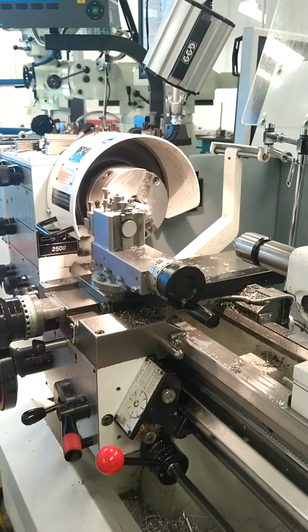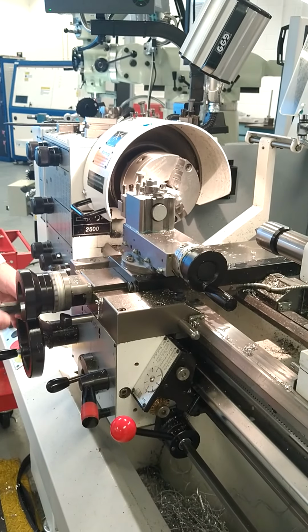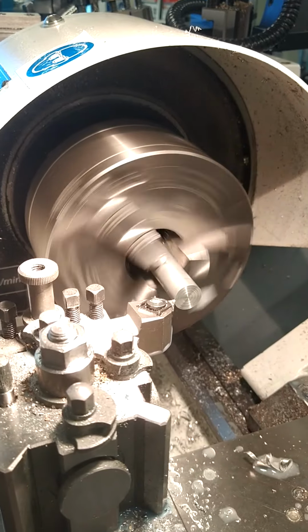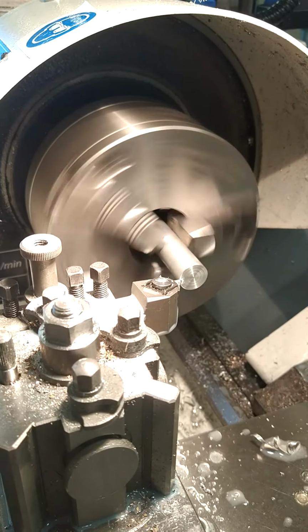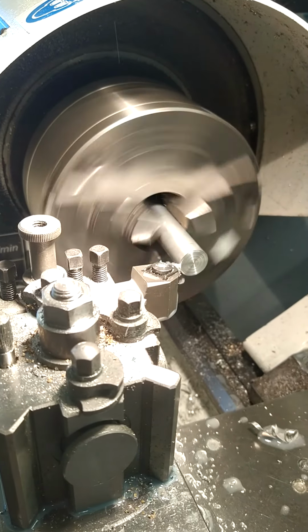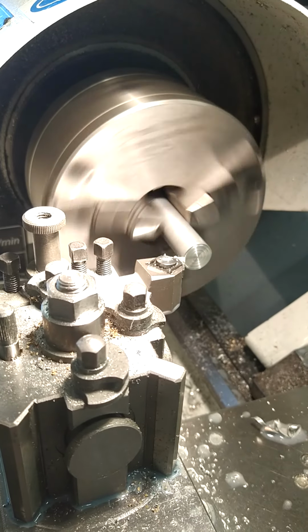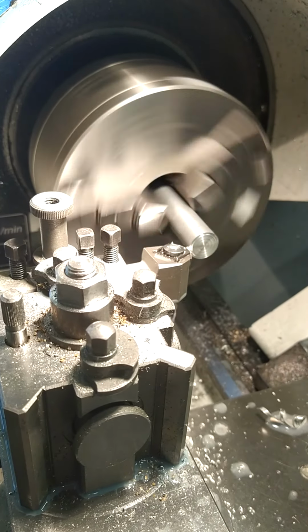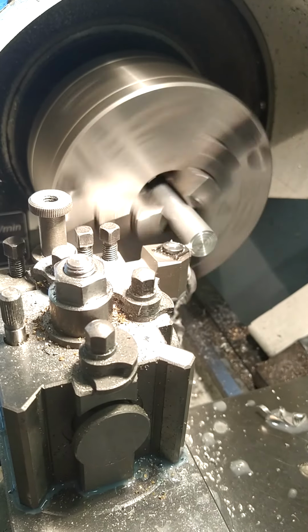So powering on the machine, just to show you how automatic feed works. Engaging the lever now, and it's automatically machining across, facing the part. We're going nice and slowly just for this video's purposes. And you can see the difference: we're getting a nice continuous chip by doing it automatically versus doing it manually. You're going to have a nice continuous chip and generally a better finish on the parts when done using automatic feed.